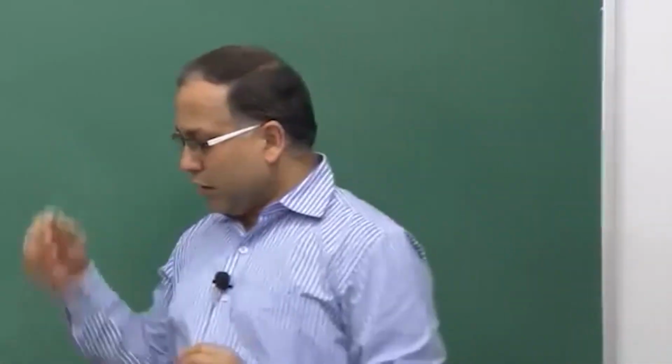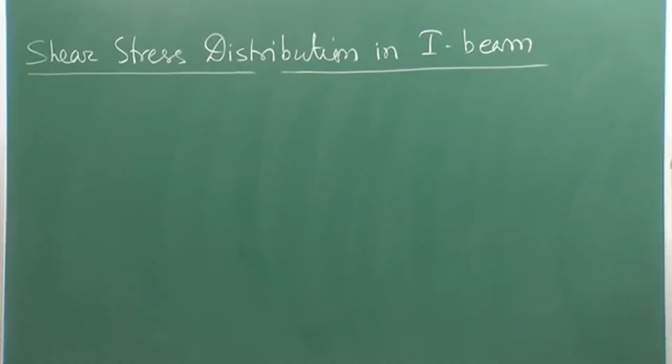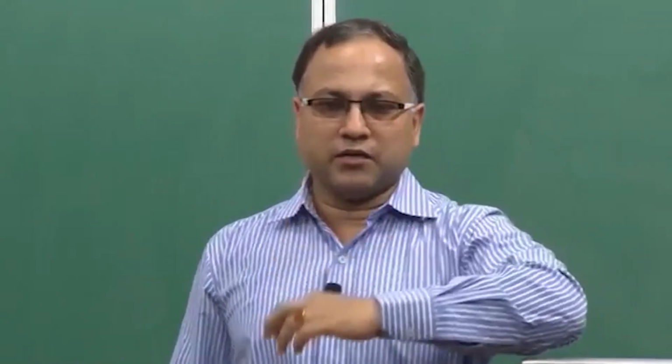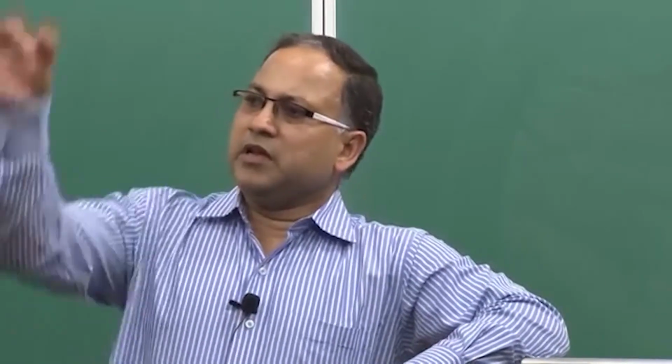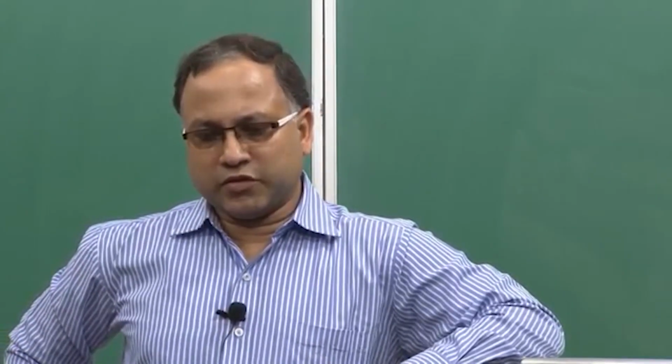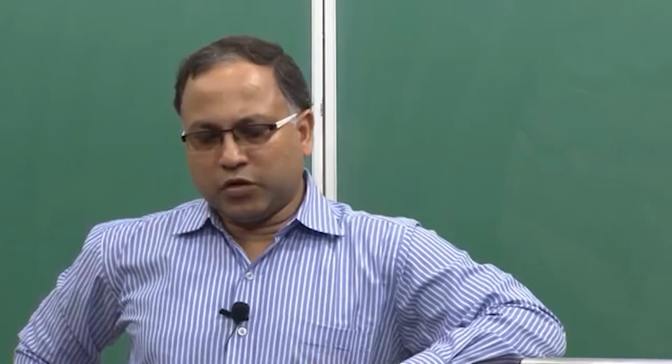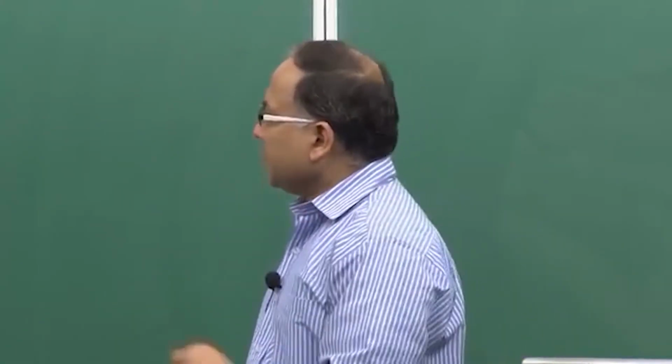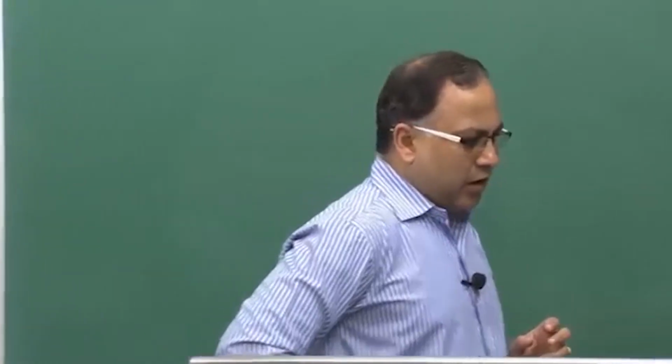Now, today I will be talking about the shear stress distribution in I beam. As I told you, I just touched upon in the last lecture, if you recall, that I beam or T beam has some speciality. The speciality is that it is not a solid cross section like a rectangular cross section. It has a very thin web and wide flange, right. So, with this kind of structure you need to analyze the shear stress distribution in the flange particularly.